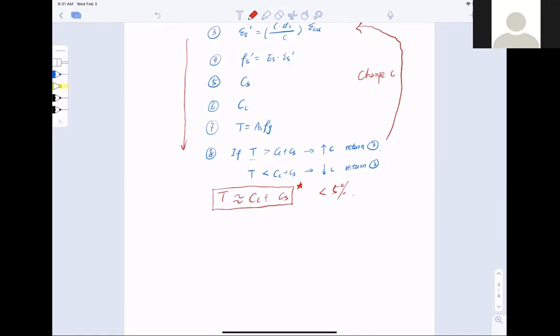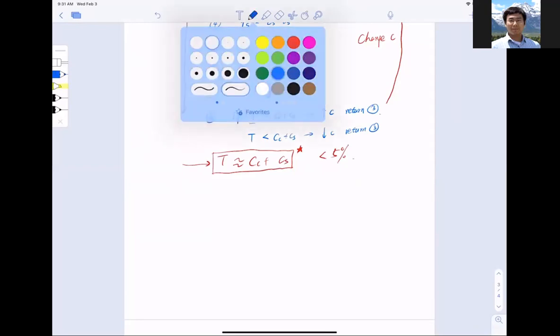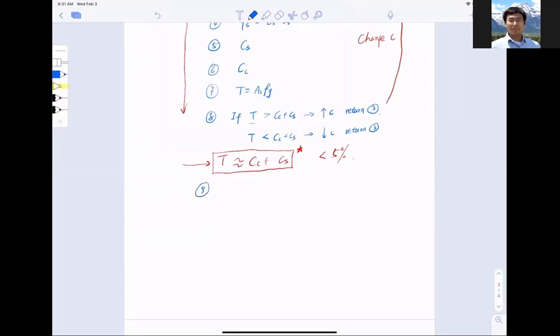Yeah, all right, no problem. So here is a critical decision point, whether you satisfy this equilibrium or not. If this is satisfied, that is, if you satisfy step 9, check again the strain in the tension side. This has to be bigger than the yield strain. And if this is the case, then you find the phi strength reduction factor by what?